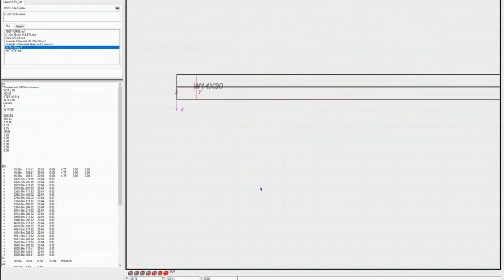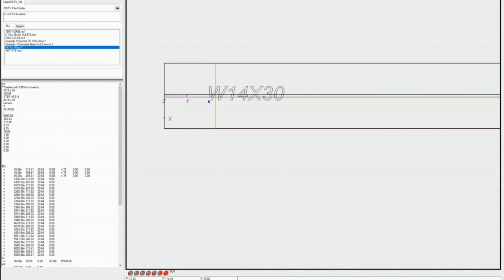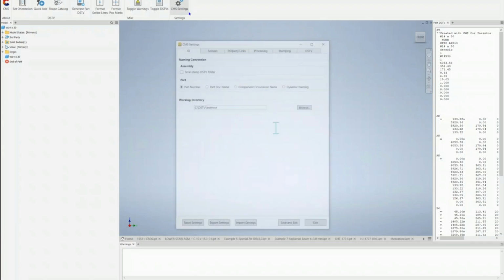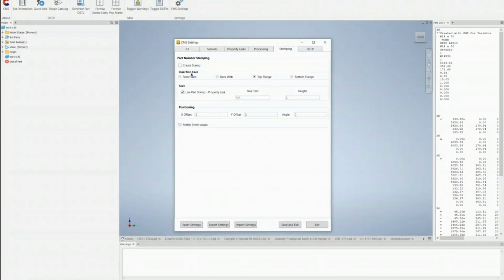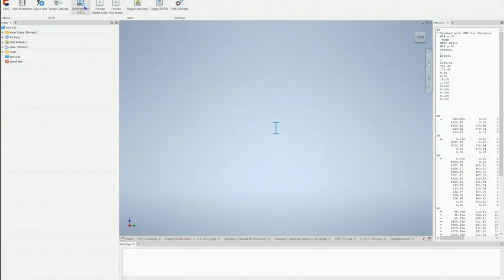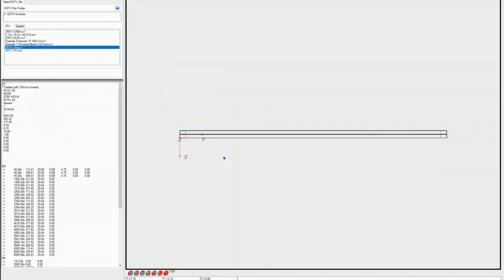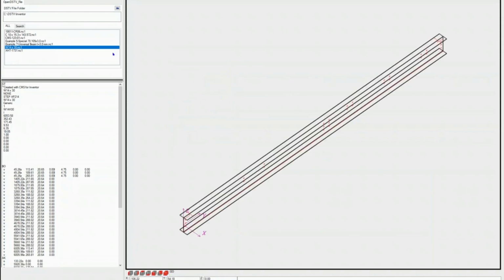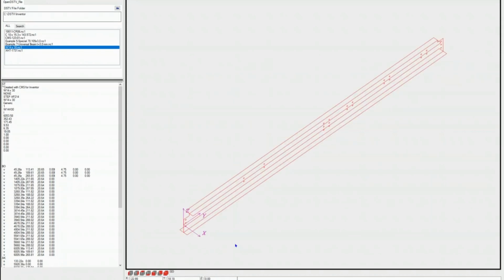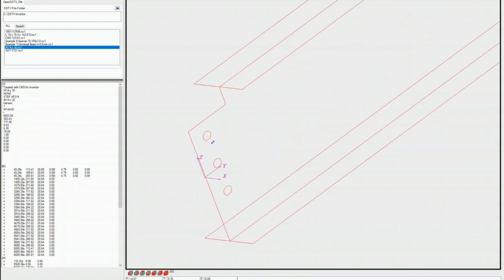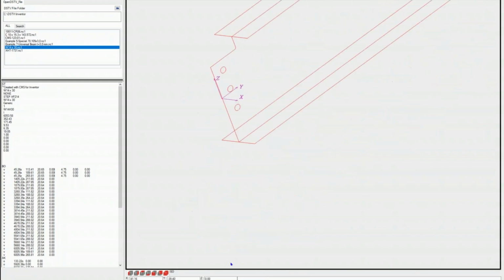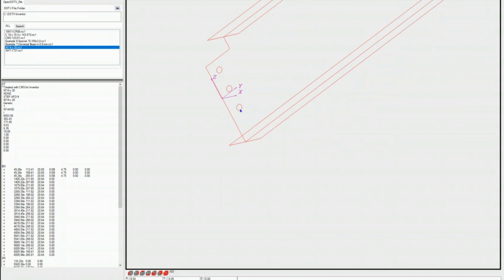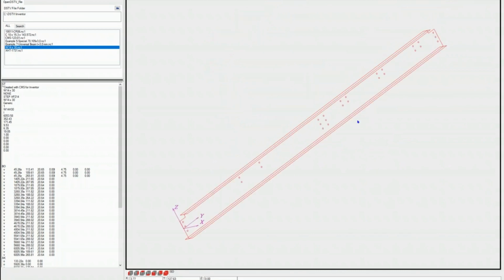As you see, the stamping, because as you remember, I have a default stamping, right? So if you don't want the default stamping, all you have to do is come over here and turn off the stamping. I don't want that. And if I rerun that, I'm going to have a new NC1 file. If I go to the viewer and click again, that thing will be gone, as you see. And then if I remove the shape lines, I just want to see my CNC line. As you see, that's a clean representation, and the slot has even been captured correctly.